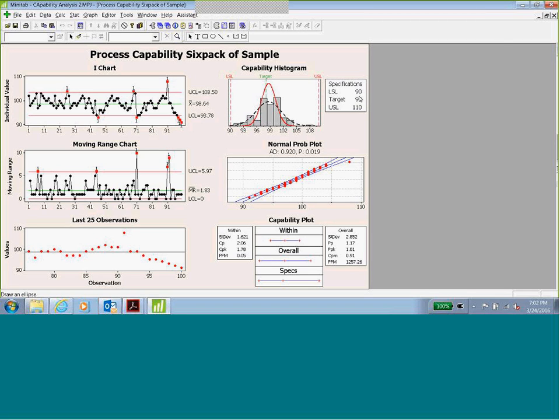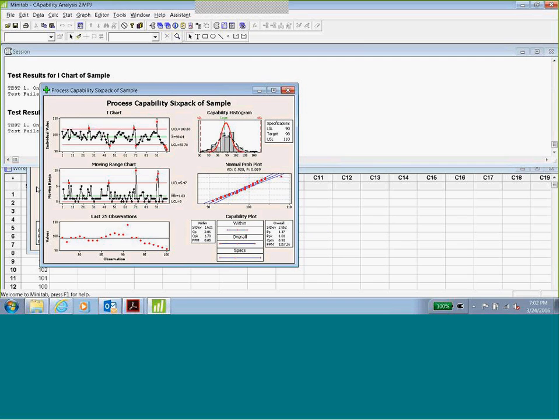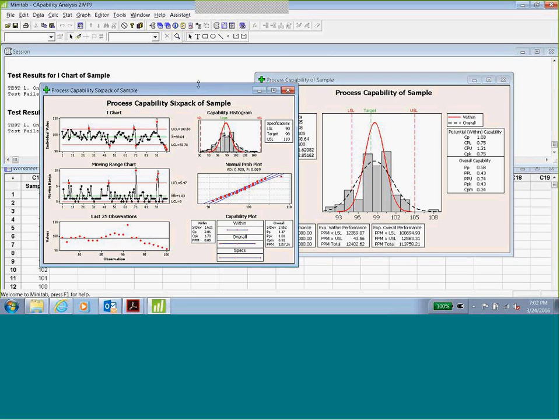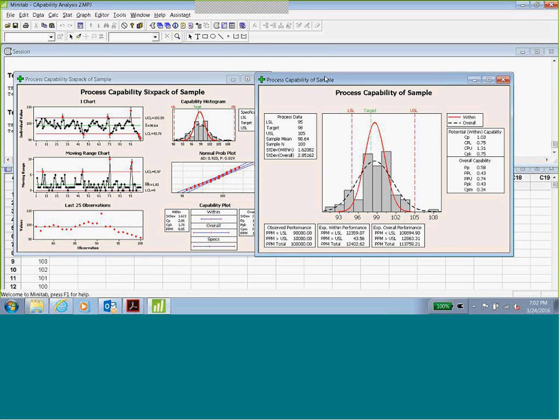What I did is I modified the data a little bit for this. So I changed the USL and LSL, and because of that, I got my CPK value greater than 1.78. In my previous case, my USL and LSL were different, and because of that, my process was outside the specification limit. So for this analysis, I just changed the limit and played with it, and I brought the process within the specification limit, and because of that I got my CPK value greater than 1 here.